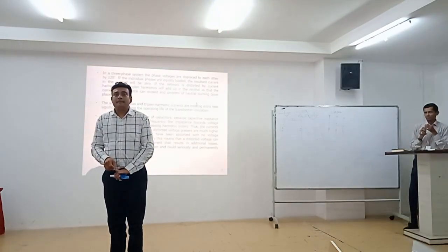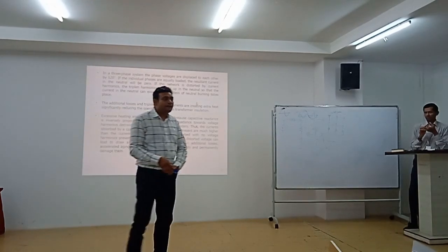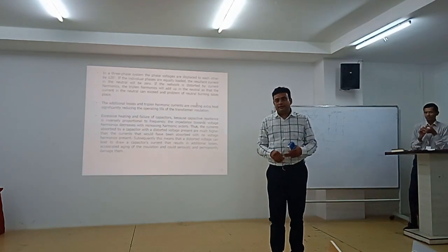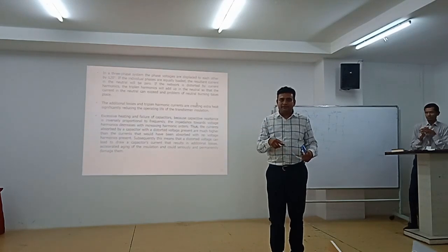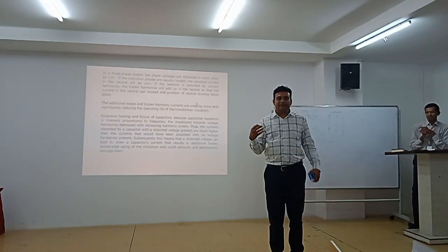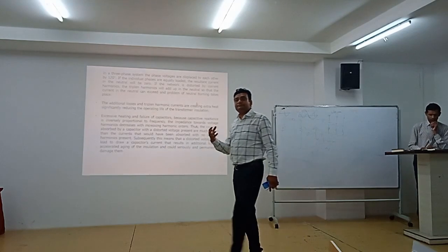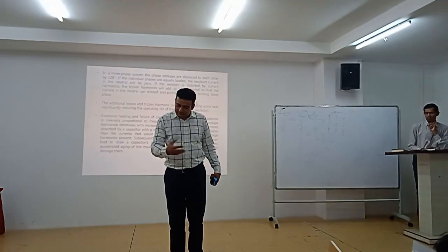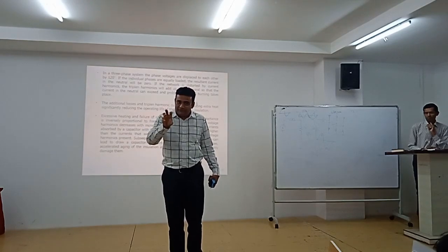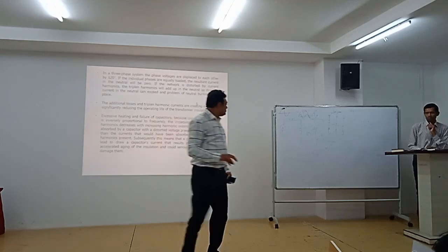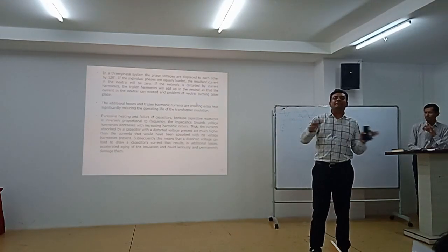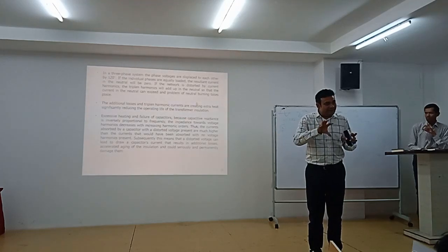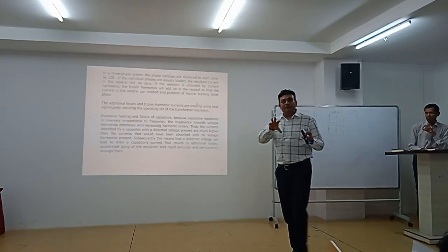What is skin effect? Current will try to take a path other than its central uniformity. Current has a tendency to flow on the outer surface only, because the reactance in the middle is heavy. So what is XL? Inductive reactance, the opposition. XL is 2 pi f L, so it contains a frequency component, right? When frequency increases, suppose at the 7th harmonic, it becomes 2 pi f7 L. So naturally inductive reactance will become dominant, right?